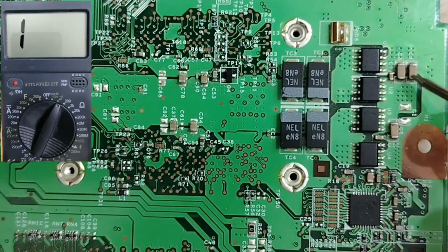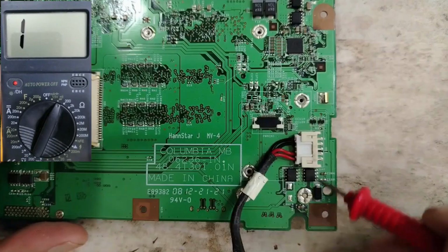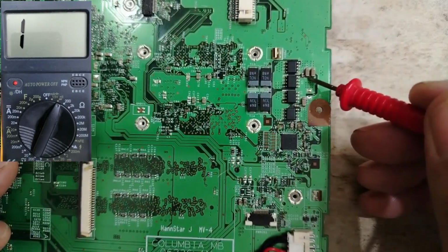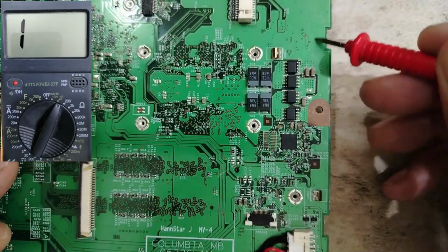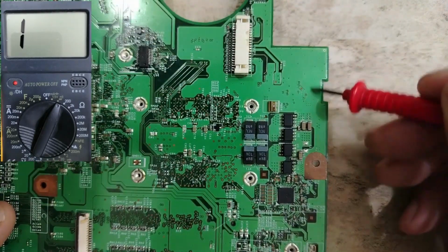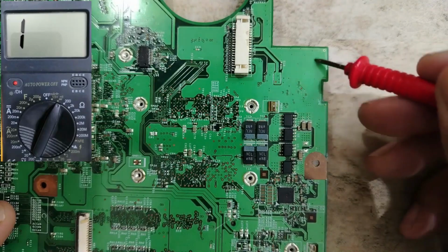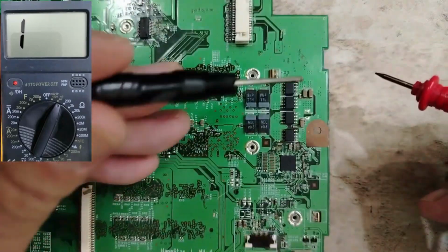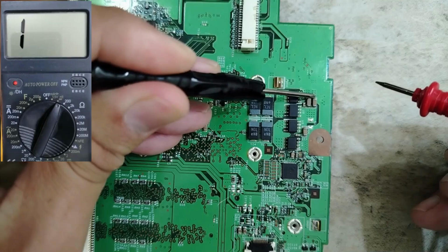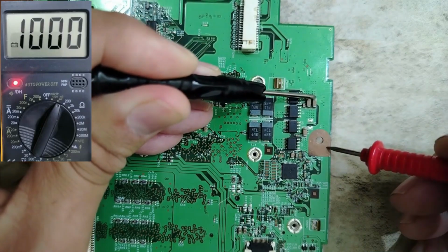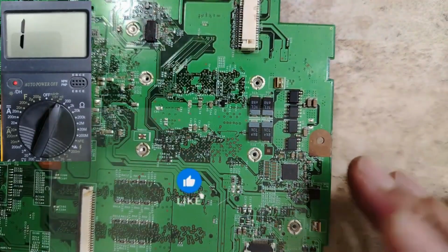So as you can see, these ceramic capacitors are connected to the input signals on this side, as you can see here, and to the ground on the other side. So here we have the ground. This wide area means the ground. We can even check if we put one probe here and put the other on the ground, as you can see in the multimeter.